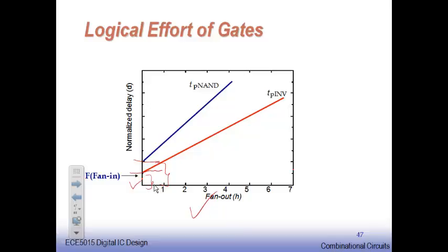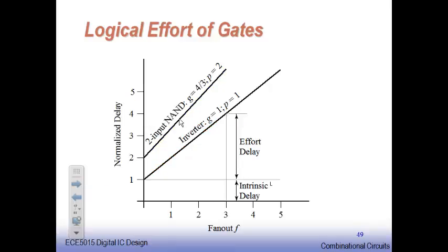Why? Because of the inherent delay it will incur by its own structure. Okay, its intrinsic delay, that would be this. And for the inverter, this one, for the NAND gate, a higher load, so a higher inherent delay, and then it goes for increasing more steeply than your inverter, naturally. And similarly, for the NOR gate, it would still be worse. Okay, all these you can go for configuring, constructing and finding out the delay and all you can do.